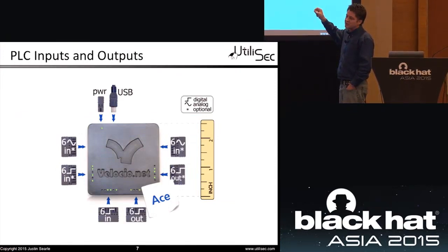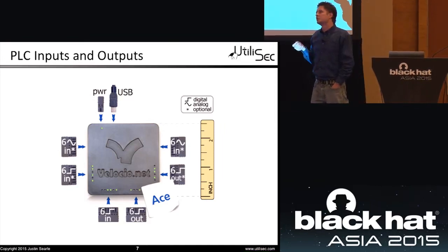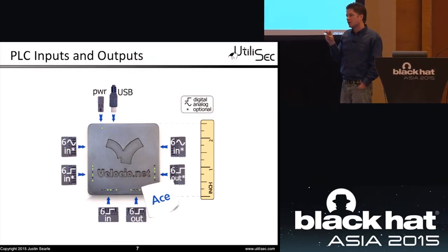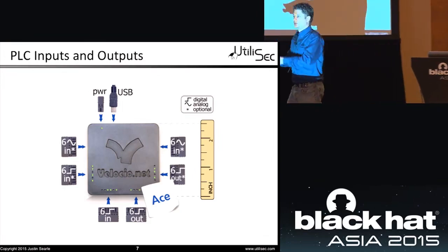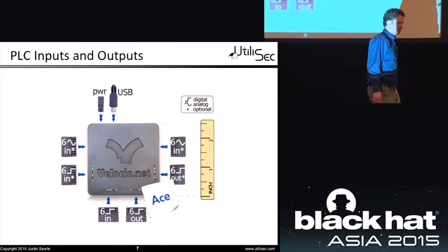So most PLCs on the lower lines do not have Ethernet ports. The least expensive PLC that you can buy with an Ethernet port usually runs right around $300, $400 US. So most of them have an RS-232 serial port on them. This one actually does it via the USB port, which is nice because, like I said, all of us have USB ports. And so it's very easy to communicate via Modbus via that USB port. So that's one thing I really like about this PLC. And if you want to see the PLC? Oh, they're indestructible. They're built that way.